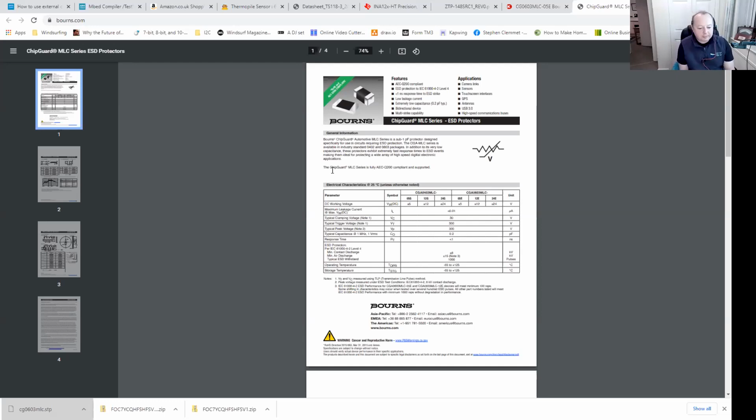And you shouldn't really be mixing your TTL and your CMOS because they do have different switching levels. You could end up in that race hazard issue where things change and you get a spurious data result coming out of it. So yeah, there are different technologies. CMOS and TTL are the two most common ones.